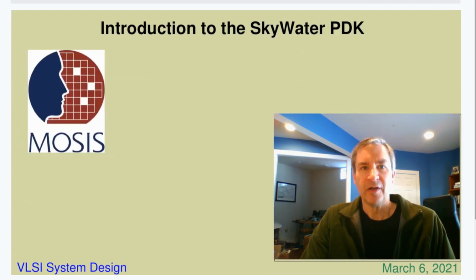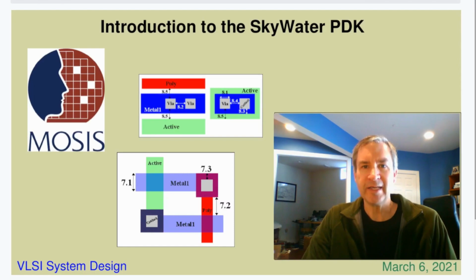In the past, for a long while, starting in the 1980s, the MOSIS Foundation in California made available the open source Scalable CMOS, or SCMOS rules, which worked with a number of legacy foundries with processes in the range of 2 microns down to about 0.18 microns. But since they've largely stopped supporting scalable CMOS in the past few years, there remains essentially nothing except for a handful of so-called academic processes like FreePDK45. It is very unsatisfying to work on development of a process design kit for a process that can't be manufactured, which is why I've never done it.